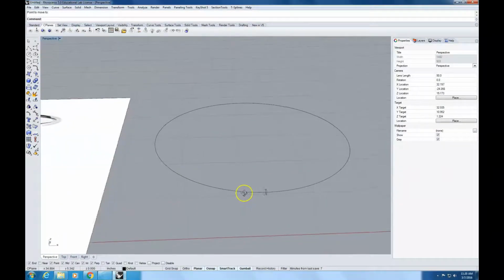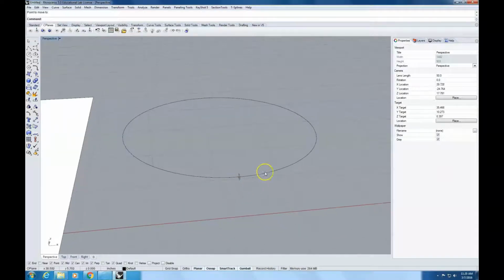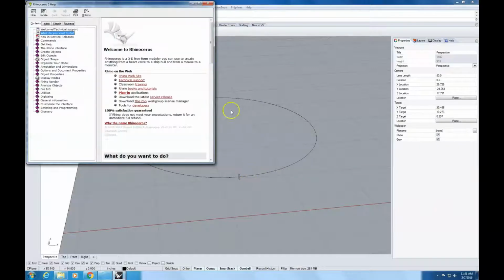So now in Rhino, if you want a shape to follow a path, it's called a sweep. Okay, sweep. So I'm going to type sweep 1. Okay. Technically, it's called a one-rail sweep. A rail is the path, like a train rail. And then the shape will follow that rail, right? So right now it's asking me select rail. So that's my rail. Enter. Oops. What happened? Select rail. Enter. Oops, sorry.